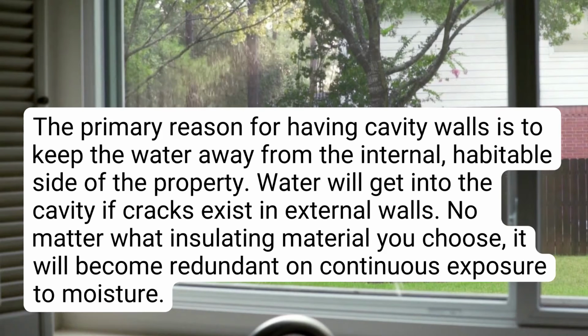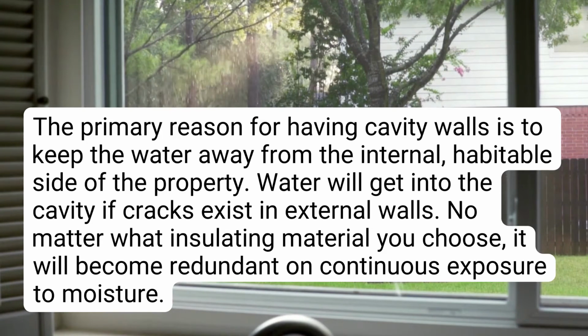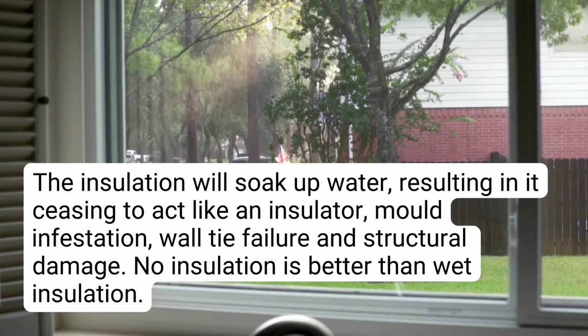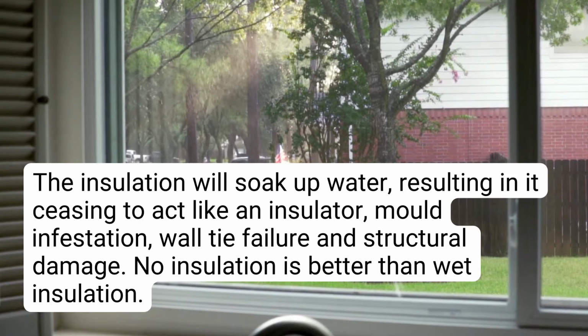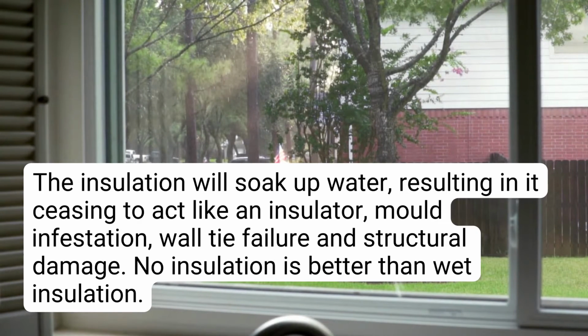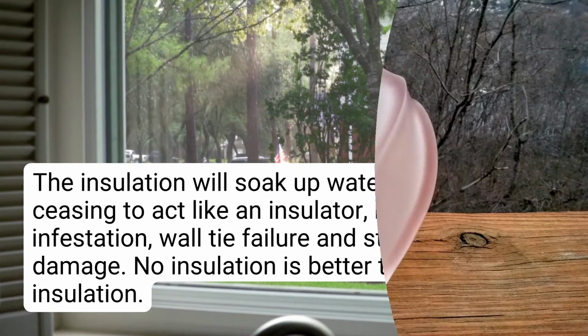No matter what insulating material you choose, it will become redundant on continuous exposure to moisture. The insulation will soak up water, resulting in it ceasing to act like an insulator, mold infestation, wall tie failure, and structural damage. No insulation is better than wet insulation.